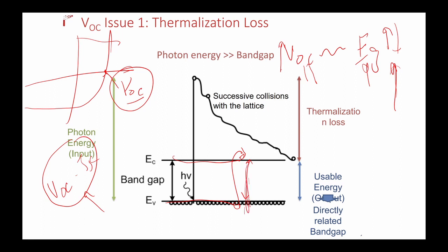What if the energy of the light is more than the band gap of the semiconductor? The electron is transmitted to a much higher energy level in the conduction band, and this extra energy is wasted as heat in the semiconductor itself.